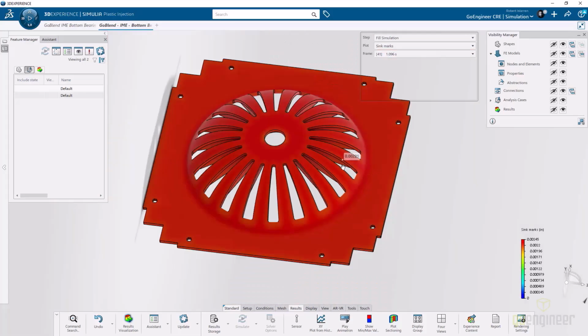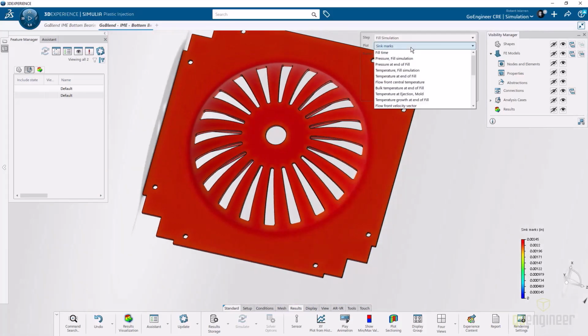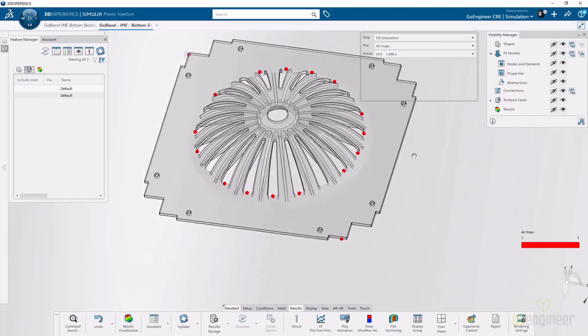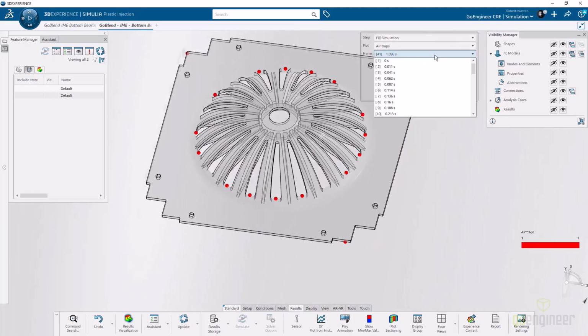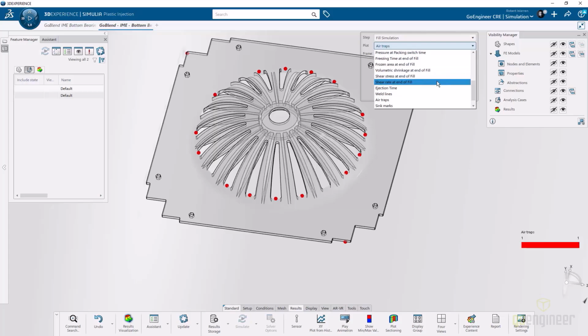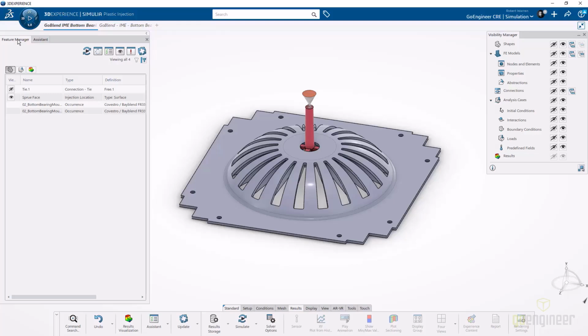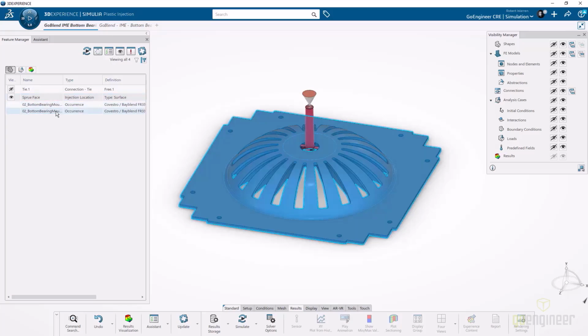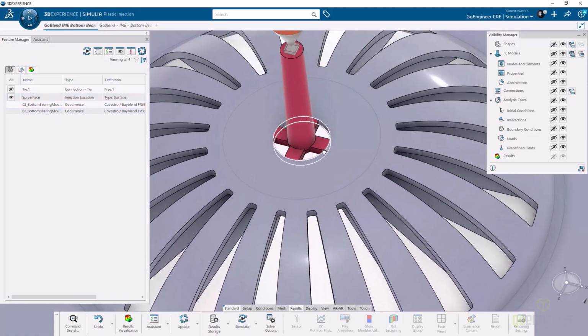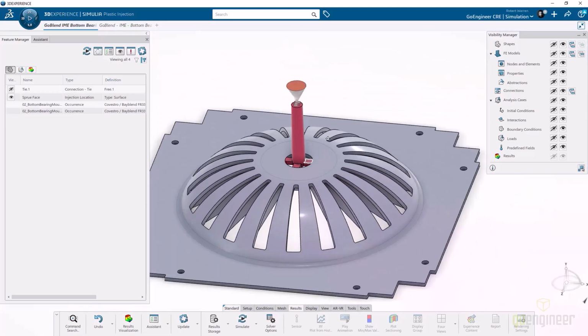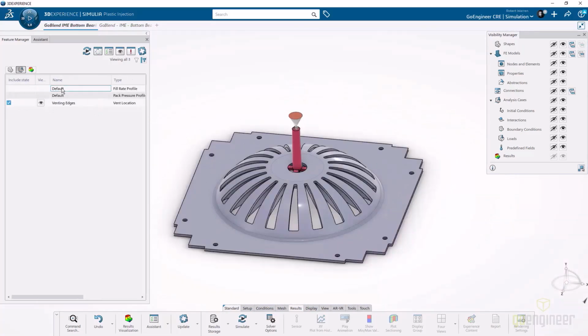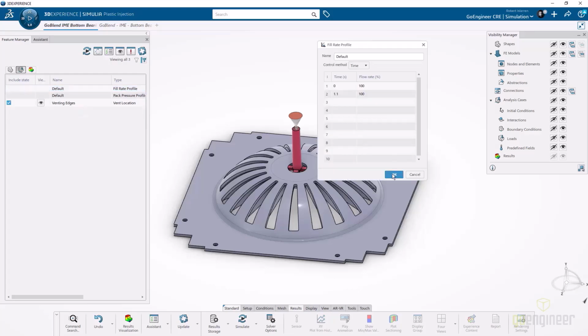So what we're going to do is we're going to switch. I actually talked to our injection molding engineer, Bill, and he said, you know what, switch to 4 gates. That's what I would recommend in this analysis. So that's what we did. So he actually guided me through this, and we switched to a 4-gate system with a sprue and 4 gates coming directly off of that sprue. Now the nice part about this is, through Bill's advisement, this actually had a lot better benefit.